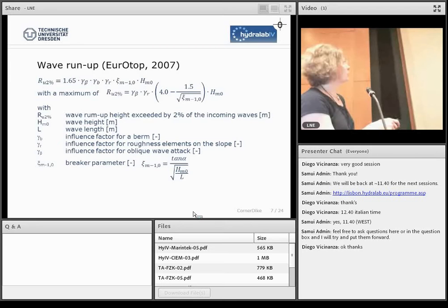And these 2 legs of the dike had an angle of 19 degrees to each other, and the whole structure was shifted a little bit so that there is an angle between this P dike and the wave generator of 50 degrees. And at this left side here you can see the wave generator from the DHI, which is 22 meters long.